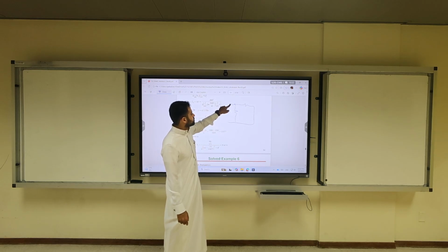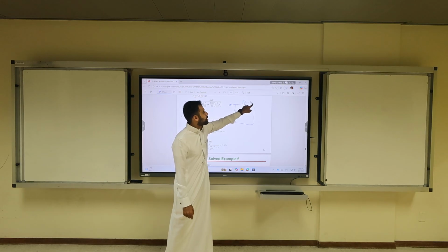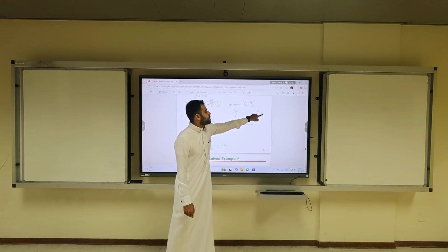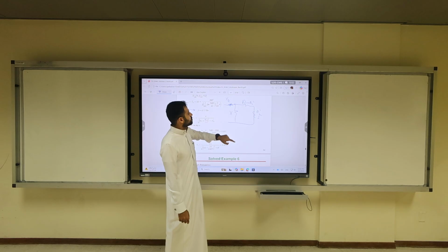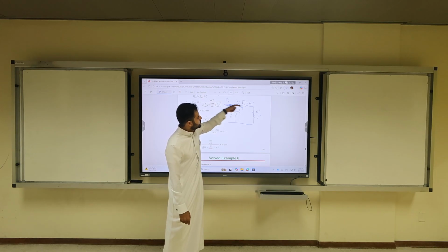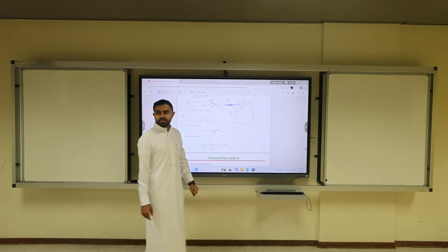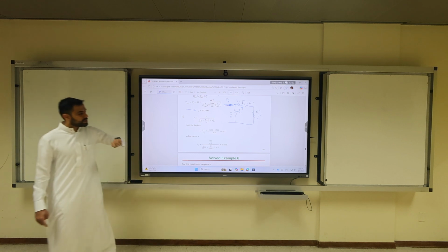Circuit 1 or 2? No, he's putting R1, this is R1 plus R2 prime. Yes. And he's putting here R2 prime over S. And this is X equivalent here. So that's the current. X equivalent is here. On the other line, this is Xm. So this is the starting current. It's the current that goes here. Clear? It's this current. It's using circuit 2 if you go back to my 360 videos.